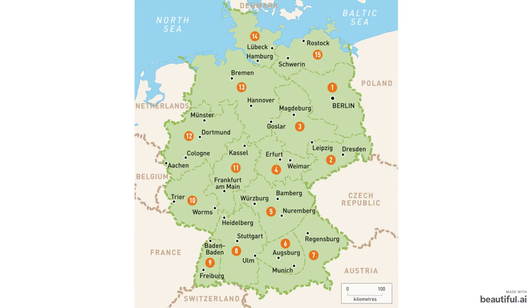So the ultraviolet light produced by the tin is then collected and focused on the wafer. So first, a parabolic mirror called an illuminator collects the light from the tin, and it's about 1.2 meters high and weighs about 1 metric ton. Now, specifically, it's a mirror, not a lens, as a lens would absorb most of the light instead of reflecting it. However, the onslaught of ultraviolet light causes the mirror to heat up, causing distortions. So sensors measure the temperature changes in millikelvins and actively adjust the position of the mirror accordingly. This is called computational lithography and has decreased the wafer defect rate in recent years.